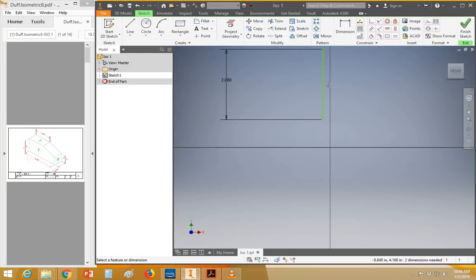You'll see once you start trying to mess with dimensions and constraints in Inventor, lots of times there's a constraint on there that you can't find, you can't figure it out, you don't know why it won't let you do the thing you want to do, and that can be frustrating. So let's go back to drawing our object here. We'll make this 1.25 just because that's the size it needs to be, and so we have a dimension on there. So we'll go back to the line. Yeah, let's erase this and start over, because it'll prove my point to something later.